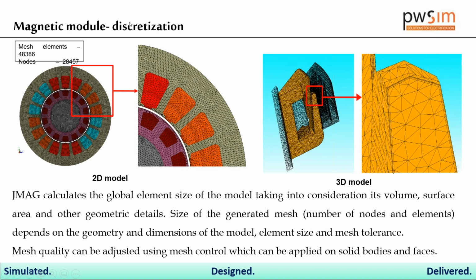Now, this is the complete essence of the finite element analysis simulation. You can see a number of triangular-shaped elements that have been formulated. These elements are, like I told you, splitting down a complex model into n number of small meshes. Each triangular mesh will be solved using its partial differential equation. And you can see that some of the meshes are very thin and some are very large. That depends upon your accuracy. Where you want more accuracy, you will fine mesh it, or thin the mesh.